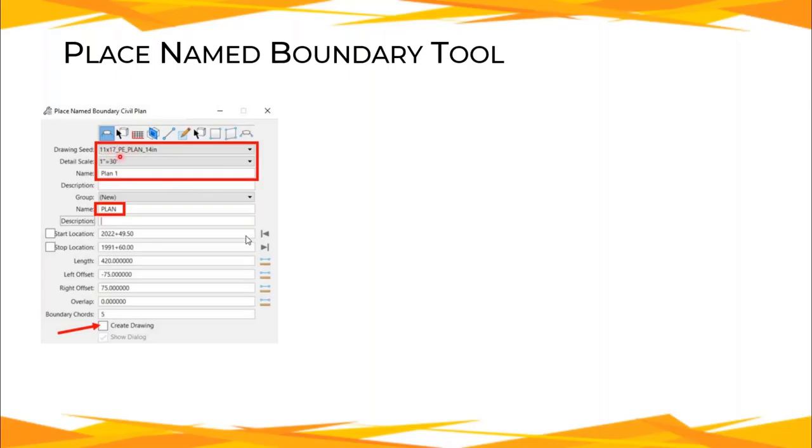In this case here, it was like an 11 by 17 plan and elevation view plan drawing seed. It says 14-inch. So what is that 14-inch? That's basically the area that it's taking up or occupying on the sheet model. So there's a certain region within the border that we can put content on. And this last number here indicates the width of the area that'll take up on the sheet.